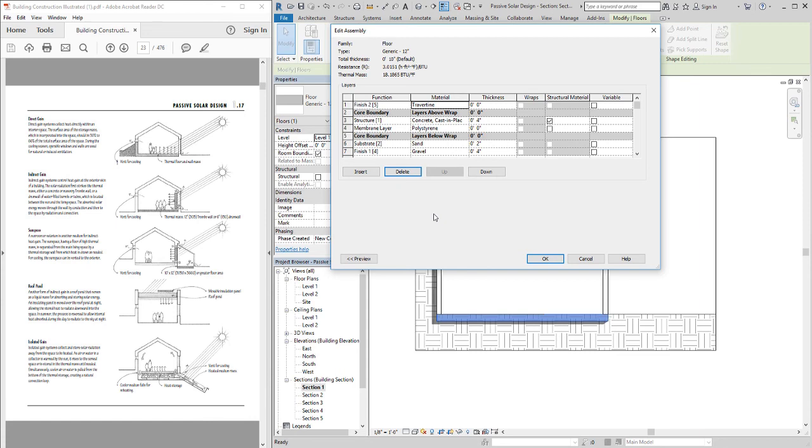I mean, you can have your thin set, and make sure that you're solid. If you have any kind of movement in your subfloor, you'd have some cracks, but here we should be all right. And people might even want to go with some kind of insulation between your floor and your finished floor. We could even insert that insulation, like a rigid foam insulation, just below that plastic. That should be fine.